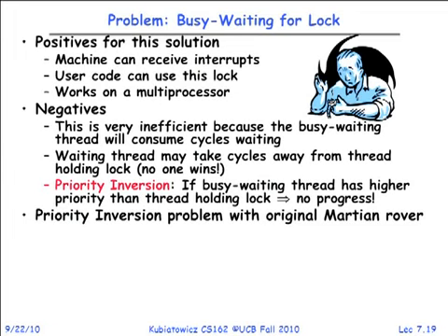So there's kind of three threads. The high priority thing really needed to run, the low priority thing had the bus, and the medium priority thing was spinning. Nobody makes progress. Fortunately, they had been smart enough with the Mars rover to come up with a monitor system that said, oh, no progress being made, better hit the reboot button. So it would reboot and start over again, and make some more progress before it locked up again. Fortunately, they had thought about this, and the rebooting was actually a positive thing in this instance. But it was a priority inversion issue.